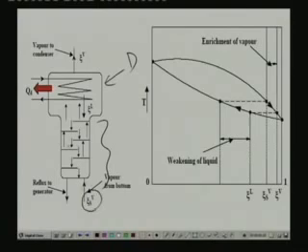The vapor that is entering into the deflegmator is nothing but the vapor that is leaving the lower portion of the rectification column. So that enters into the deflegmator, and let us say that it moves up, and at the upper portion it rejects some heat to the low temperature heat sink. So this is the heat rejected in the deflegmator, QD.